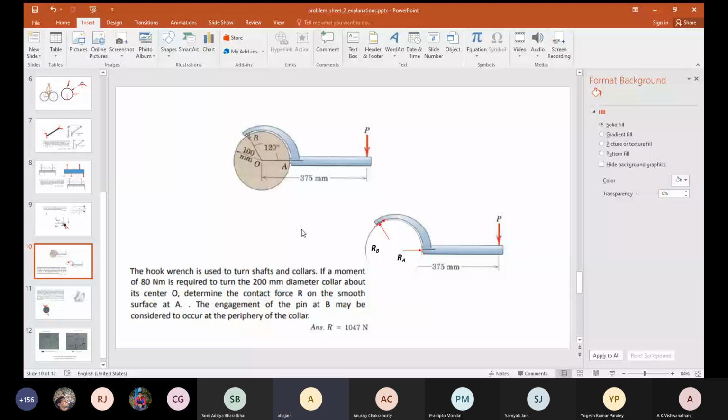Sir, when you're looking at the structure as a whole, then how, if we had a question to calculate the tangential force at point B, how will we do that? I would do it like that. I would take moment about B, find the value of RA. I already know P. Summation Fx is 0, Fy is 0. Get the two reactions at B. Okay, okay, sir.